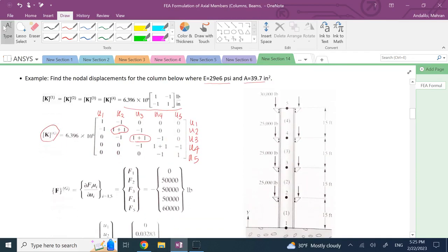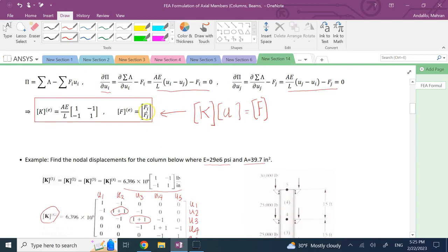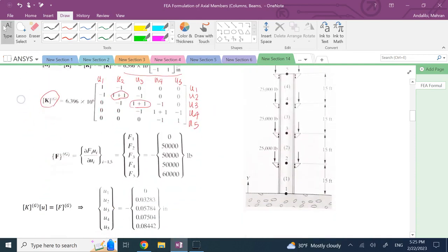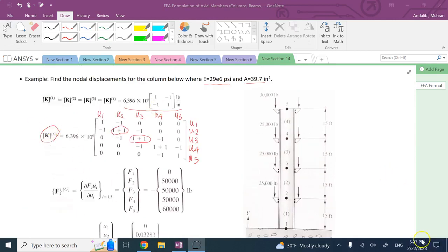Then clearly the F's at the two ending nodes are the loading vector for that element. Therefore, if I want to calculate the nodal loads, they are going to be these numbers that you can see. On node 1 there is no load, on node 2 there is negative 50,000. You might say, where's 50,000?